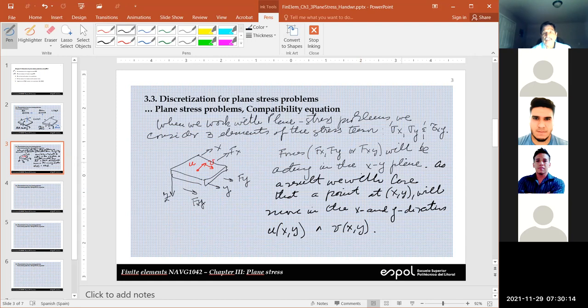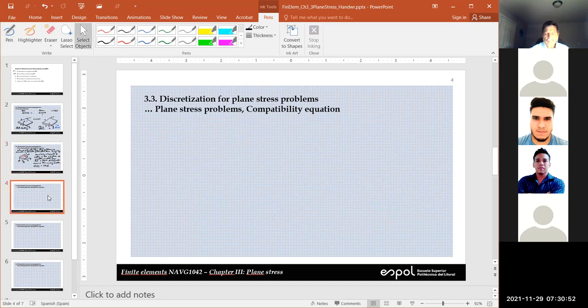The problem is that we are interested in these three components of the stress. You see, I have two displacements here, and these two will define three stresses. This difference in number forces us to deduce a relation so we don't have strange results. That's why we need a compatibility equation. So let's continue with our review of some basic relations.